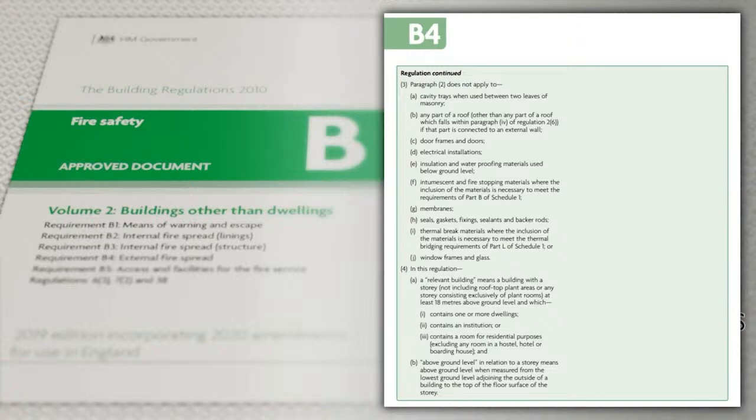Other systems are included in the list of exemptions as they are made of materials that may contribute to the spread of flame, but which there are no alternatives for. Typically, these materials are ones that occupy only a small area of the building envelope, so whilst they may contribute to the development of the fire, this contribution is likely to be extremely limited, and is therefore outweighed by the benefits provided.